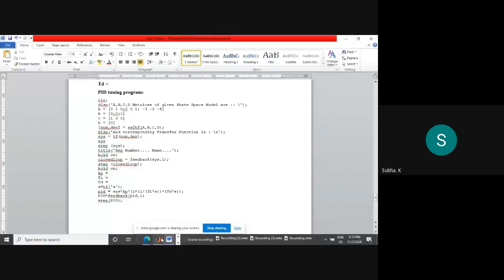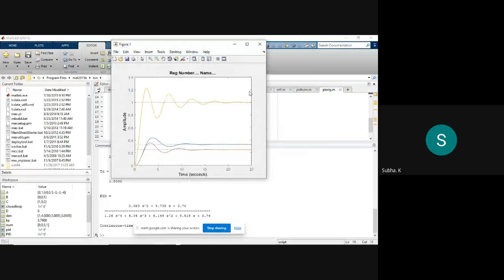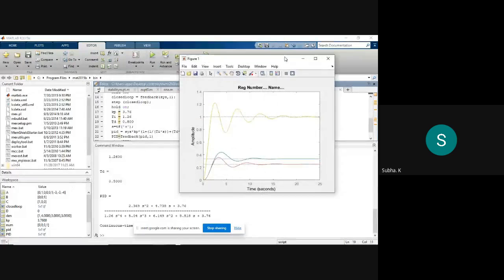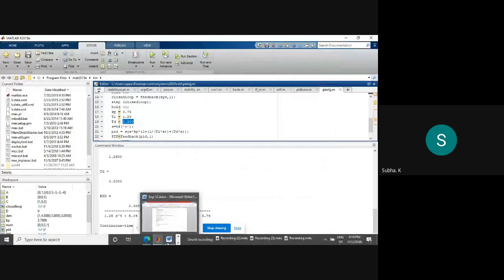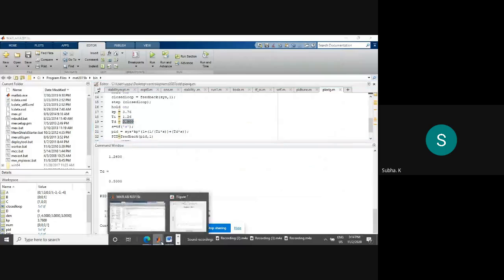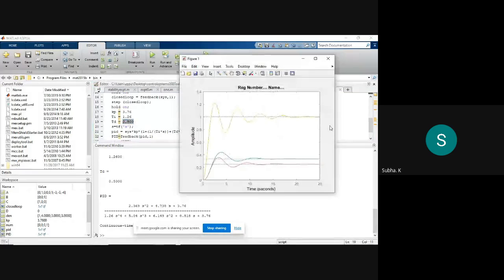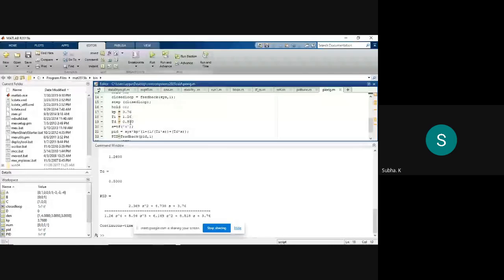See, by reducing TD also, by varying it I am getting results. TD is actually responsible for damping. So I have made some changes in TD. From 0.315, I made changes to 0.500. So you can clearly see the oscillatory behavior is overcome. Yes or no? Because you cannot simply go on increasing proportional gain, it will result in a problem.